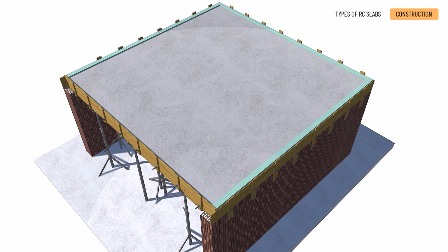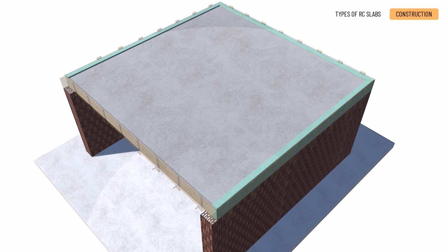Removal of the formwork. First, keep the hardening concrete moist and watered. Second, after a few days, when the slab is sufficiently solid, remove the intermediate supports and the floor props. Third, lower the primary beams with the drop heads and remove the cross beams. Fourth, remove the primary beams and part of the formwork, leaving only the props in place. Fifth, once the concrete is fully hardened, remove the entire formwork, including all the prop supports.